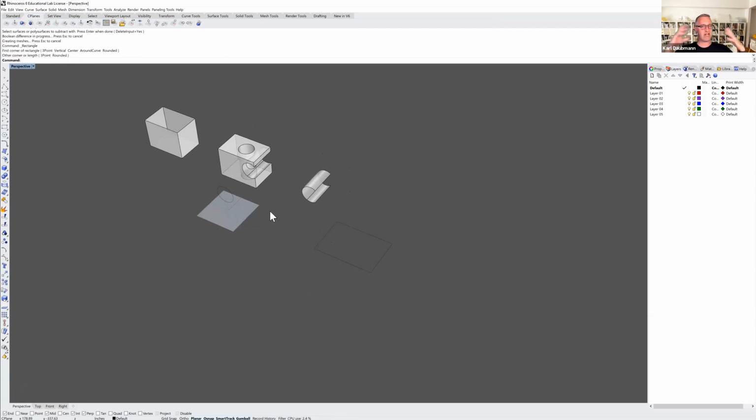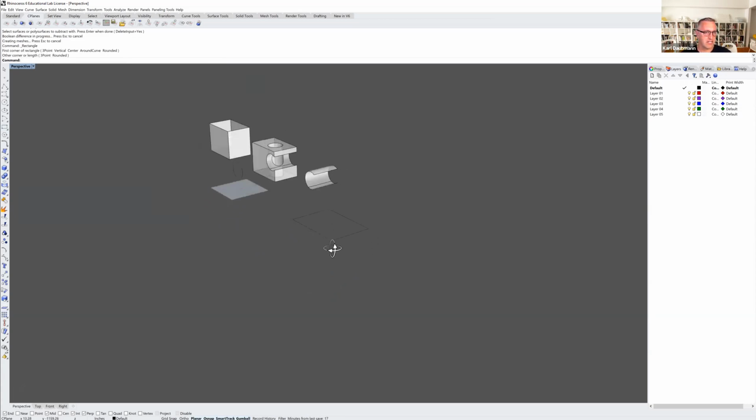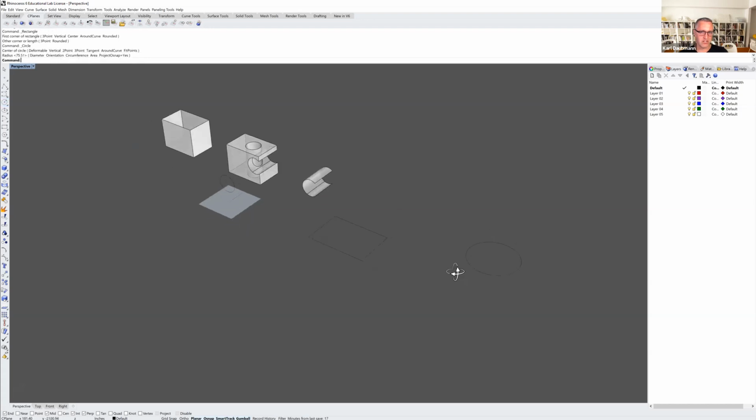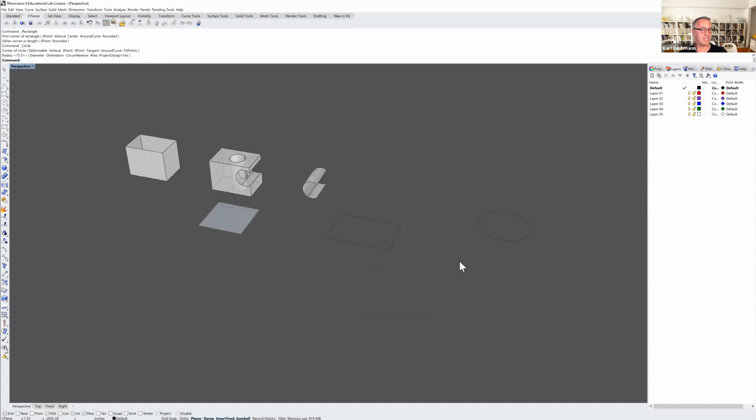And you can see when I've now moved to just work in the perspective view, in the one big view, the construction plane becomes that much more important. Even though I'm not drawing explicitly on the construction plane, whenever I draw anything in the 3D view, the construction plane where it's currently set is there. And if I'm not snapping to anything, and this is the distinction that I want to start to make now, it defaults to the construction plane.